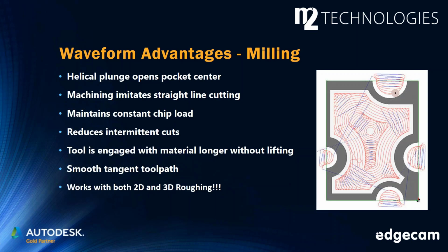Or the choice between, do I want to drill a pilot hole or do I just want to push the tool straight down into material, which really isn't ideal. While the path that you see on the screen looks kind of strange, at the end of the day, what that's doing is it's imitating straight line cutting.